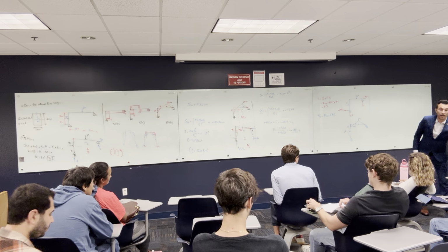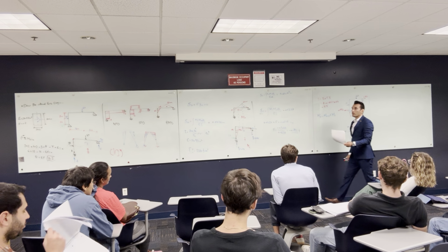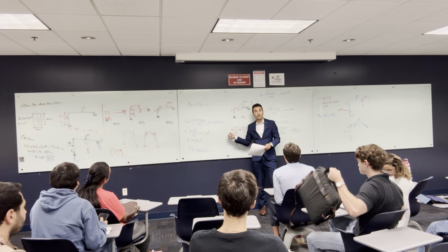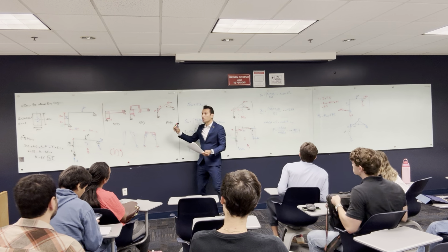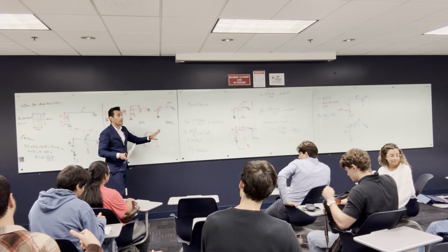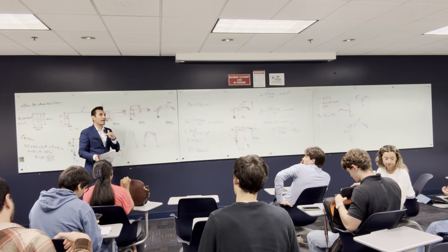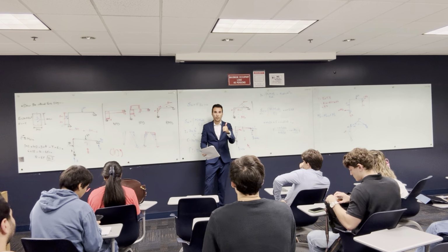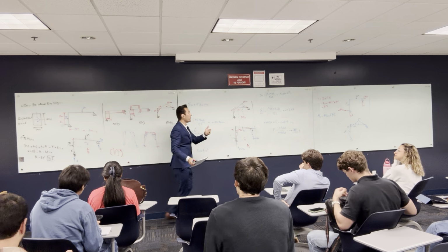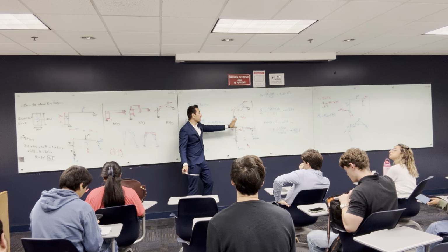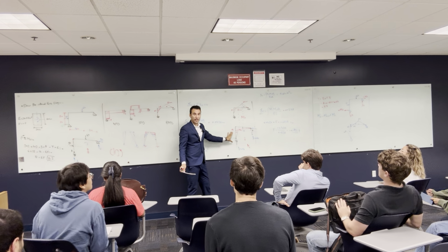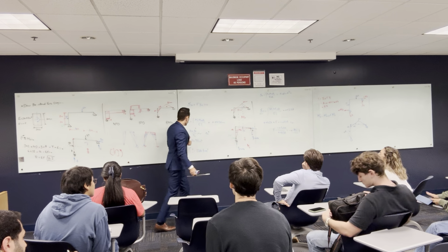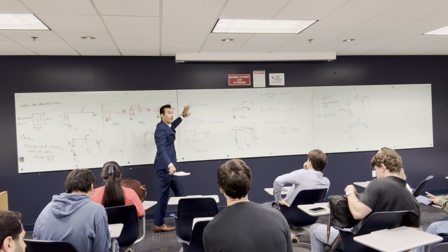So for now, I finished the consistent redundant method. There is definitely a question on this in the midterm and the final exam, worth 25 points. Try to revise and understand this very well. Think about it as steps. Step 1, choose a main system, determinate and stable. Find the redundant. Get the bending moment for the main system. Get the bending moment for the virtual system that has the unit load. Integrate them, get delta 1,1 and delta 1,0. And then substitute in the compatibility equation.